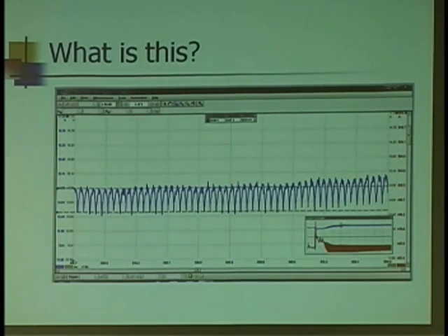And doesn't know how to react to that. Easiest way to find out, unplug the alternator, see if the problem goes away. Okay?